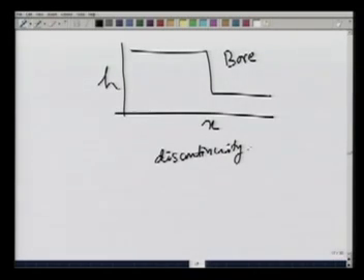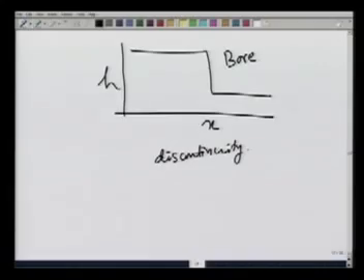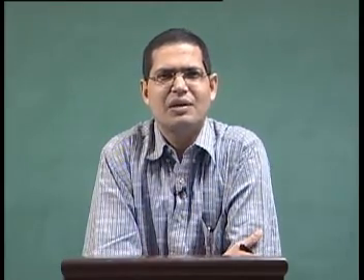So, the Lax scheme is not very good to capture a discontinuity like this. That means, strictly speaking, the numerical scheme should produce this as the result, but the Lax scheme will give you something like this. It will indicate the nature, but step-like things will come. When we get step-like things, we know that this is not a very good thing.